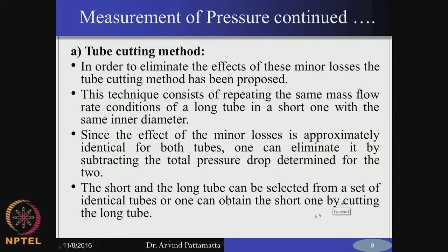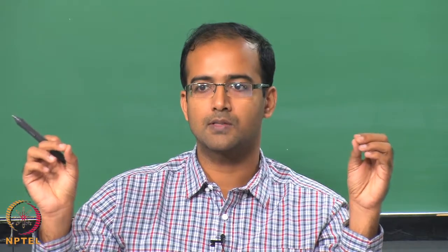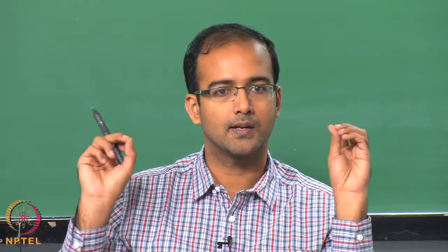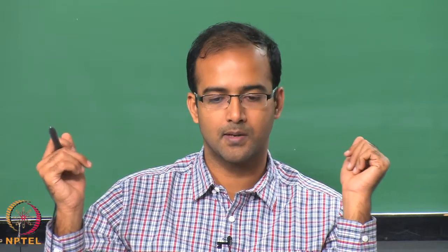Because, as we talked about, a considerable part of the differential pressure will include also the expansion and contraction losses. Therefore, if you want to calculate only the pressure difference within the micro channel, usually we keep the pressure tappings outside the channels. The inlet and outlet ports are the convenient locations to fix the tappings, and unfortunately that includes the additional contraction and expansion losses.